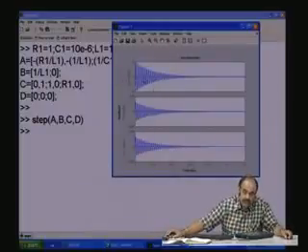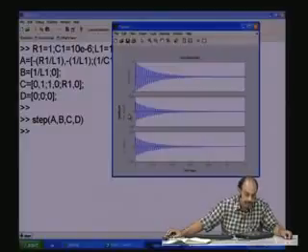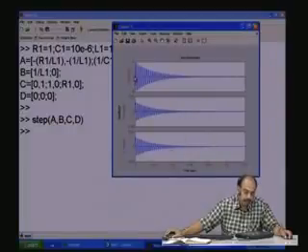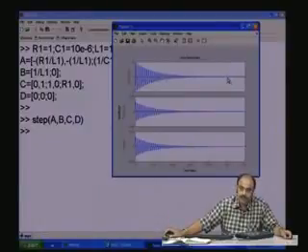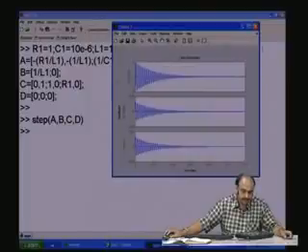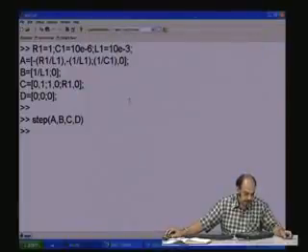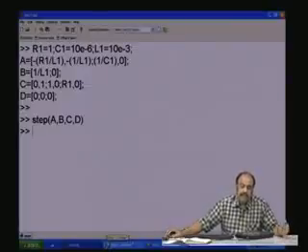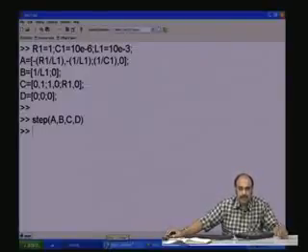The first one is VC, the second one is the current IL, the third one is the voltage across R. In both these cases, it is decaying to 0, and in the case of VC, it is settling to a value which is 1. So, in this manner, we go about doing the analysis of any given circuit, whatever may be the complexity.